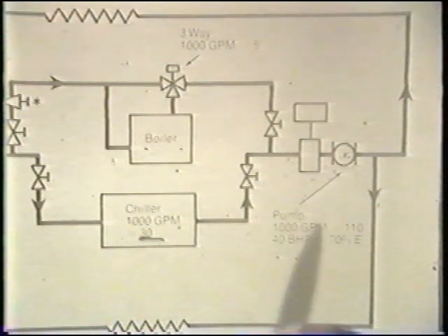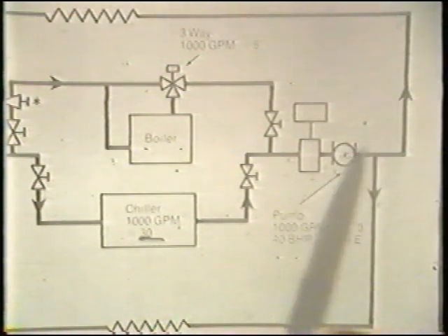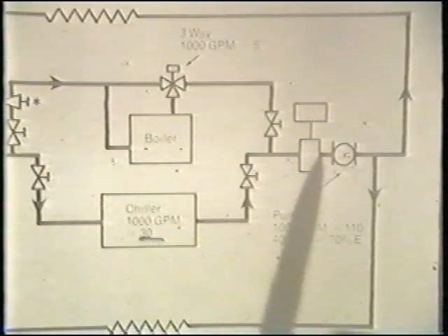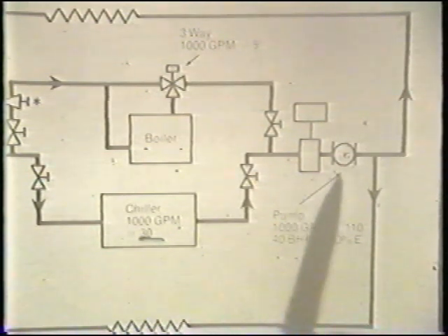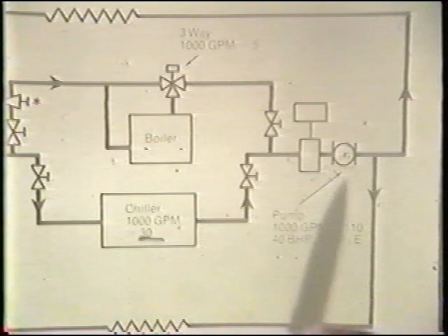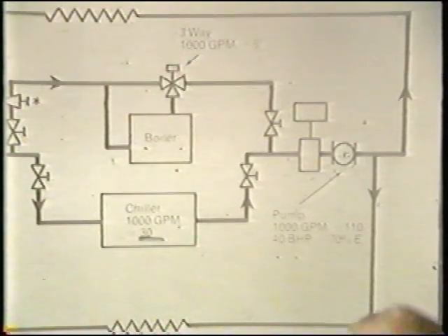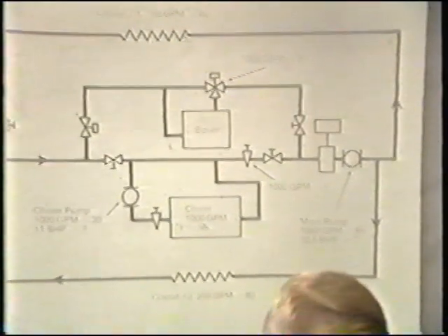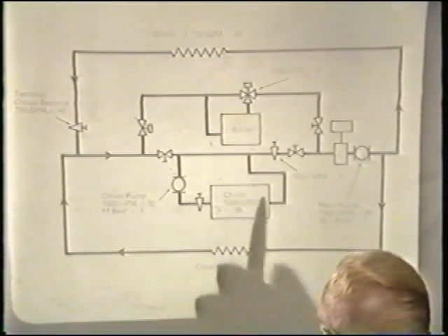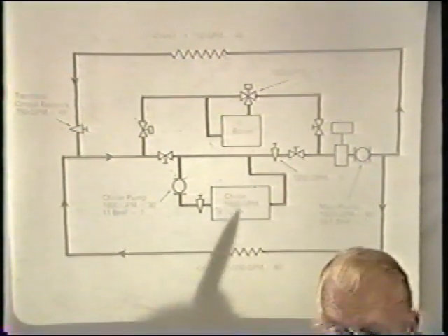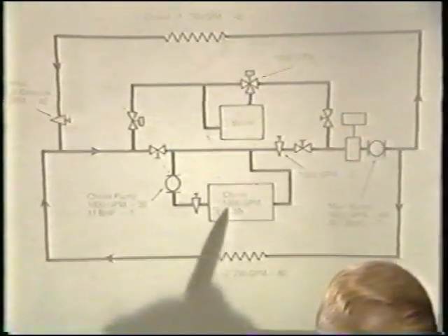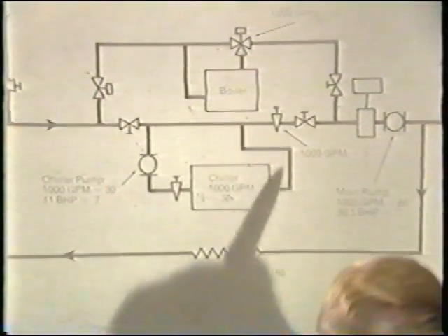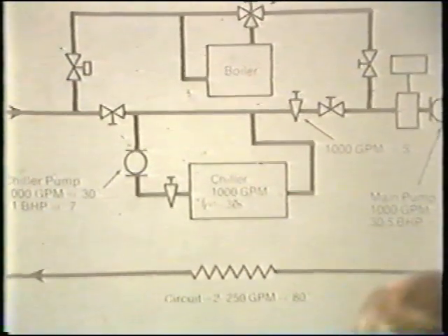In addition to this, the need for flow during the wintertime is very substantially reduced in comparison with the need for flow during the summertime. So let us, as a first example, simply replace the chiller in terms of replacing that with a primary secondary design.